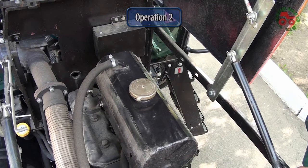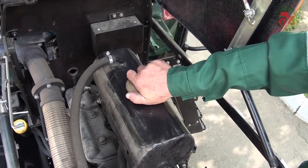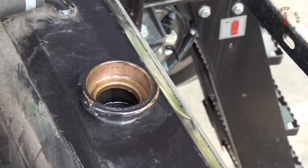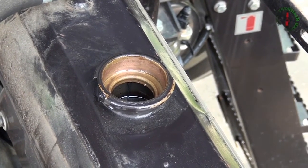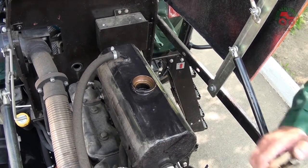Operation 2. Checking the level of coolant in the engine cooling system. To check the coolant level, do the following. Open the surge tank cap. Check the coolant level, which should be 50-60 mm below the height of the filler of the expansion tank. If necessary, add the coolant and close the cap of the tank.